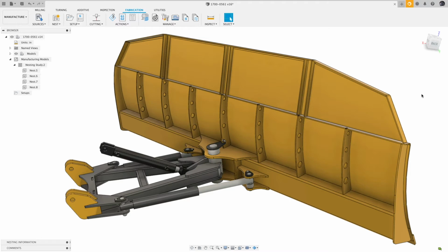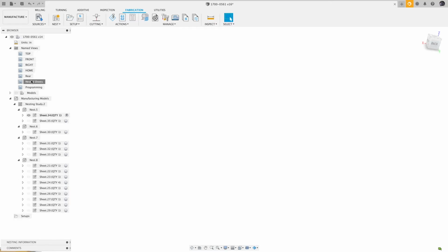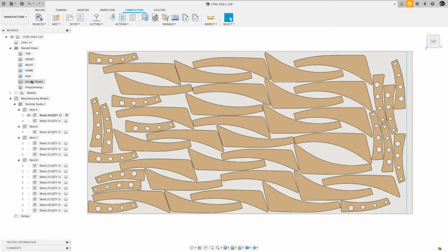If you don't go through the process of setting up custom materials, Fusion 360 will automatically create materials to accommodate all the components you want to nest, using reasonable default values to nest all the shapes. This makes it a quick and easy way to preview nested results, especially again for quoting or material ordering, but component sources and process materials offer more control and customization for production.